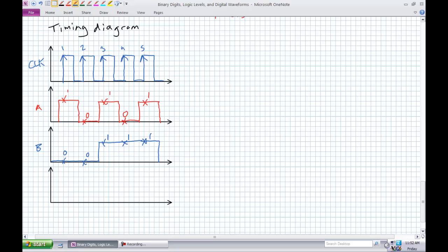Now, what would happen if my clock was going twice as fast? I've upped the frequency. Before I draw this, is my period going to go smaller or bigger? Think about it. The answer is smaller. My period is cut in half because I doubled the frequency. When do the positive edges occur now? Right there, right there, right there, and so on. I'm just sampling at a faster rate. For B, I'm going to sample there, there, there. Notice I've avoided that region right there.